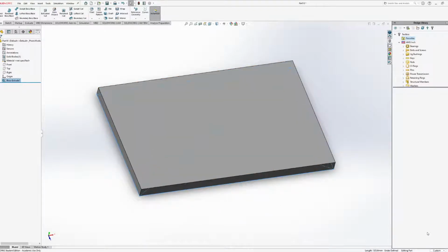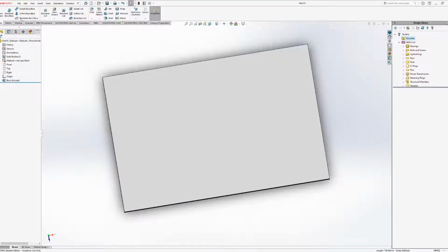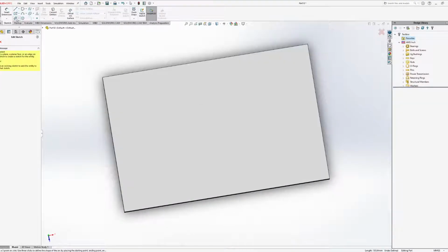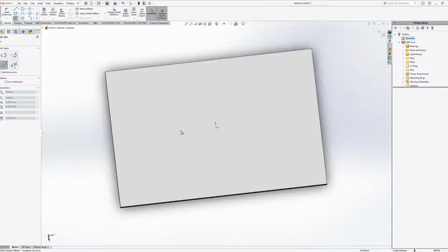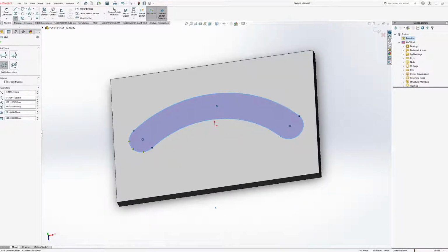Going to make sure that this is properly in millimeters. I want to sketch, and specifically for this one I was using a 3-point arc slot. This is actually pretty cool. It's similar to the 3-point arc, only I designate a specific path and then the specific radius to it, and then I go out how far I need it to be.